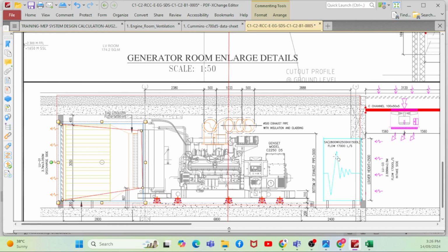And this alternator is 25 pascal and this is 20 pascal. And the duct connection will be 10 pascal. Assume like that. So 25, 25, 50, 50. This 20, 20 will be 40 pascal. So 50 plus 40 is 90 pascal. Then I have a duct connection pitch which is 100. So still I am within the limit of 100 pascal, right? Yeah. So then still I don't require any external fans.